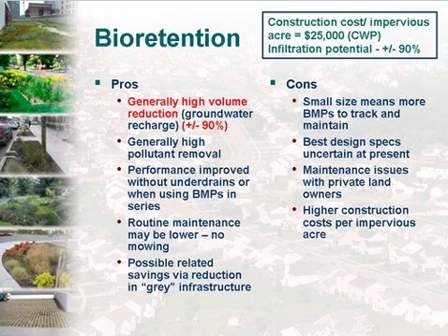Some interesting little things, particularly about bioretention. I know the center did some sort of preliminary analysis, and Tom Schuler was telling me about this, that the performance of a bioretention cell without an underdrain as compared to with an underdrain is dramatically better without the underdrain. And I think based on the stuff that we've been talking about, our audience can imagine why that would be. The underdrain, of course, is going to pull off some of those smaller events. And depending, too, on the soil mix, I think we've seen in some of the bioretention cells that decomposition actually adds some pollutants in some cases. So if it's possible to do it without an underdrain, you're probably going to get better performance.